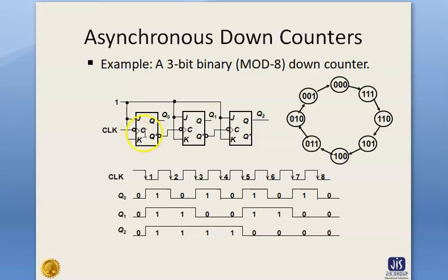If we make the flip-flop trigger input positive going edge trigger in place of negative going edge trigger, then an up counter may work as a down counter. Another one is taking the counter output from Q bar, that is the complementary outputs, and then we may get the down counting sequence. So with these three modifications of an up counter, we can get a down counter.